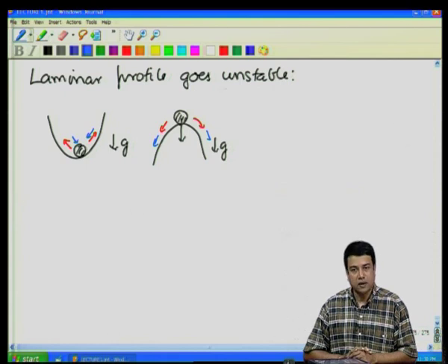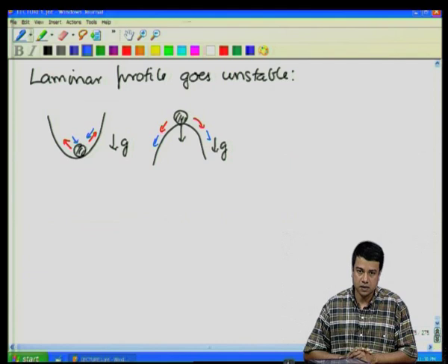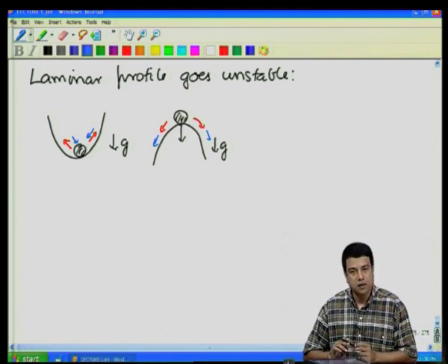If you recall, in the limit of low Reynolds number, we had said that we neglect the inertial terms, and because of that the equations end up being linear. That means that the solutions exist and they are unique. Okay. So, for low Reynolds number you can have only one particular solution. However, in the high Reynolds number limit, the inertial terms become important, and therefore, the solution is no longer unique.